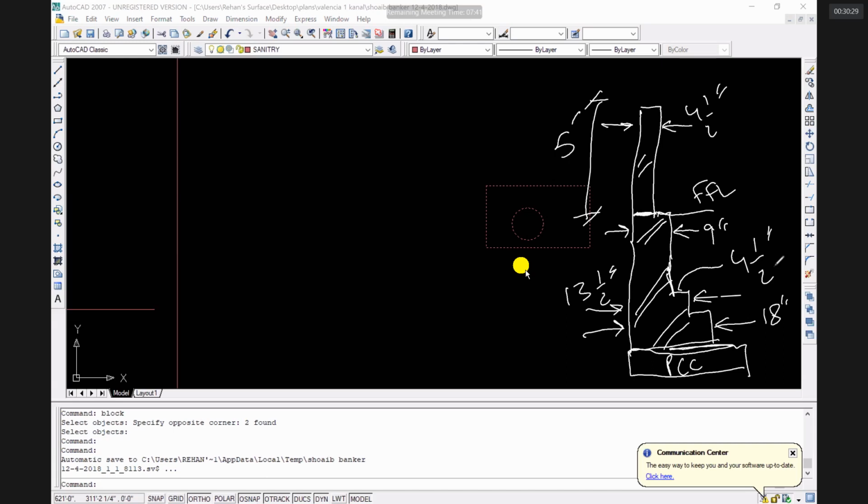Yes, the total width of the footing would go on one side. You are right. Instead of 2.25 inches, you would extend 4.5 inches on one side. You are right. So is your question answered, 103?